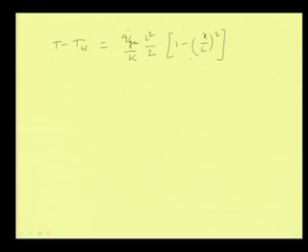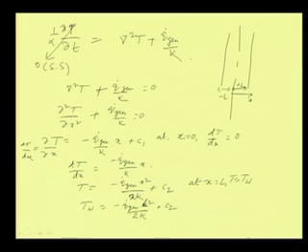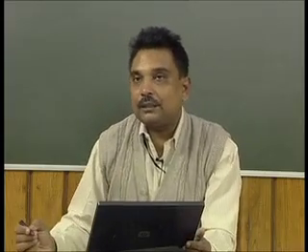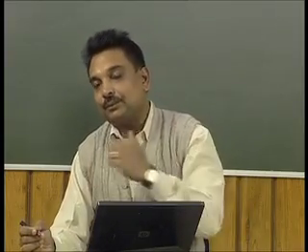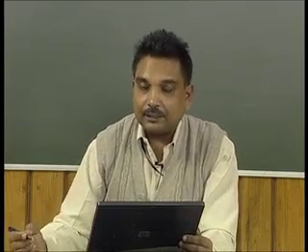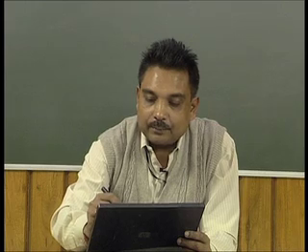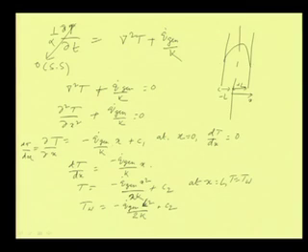This becomes the temperature profile in that plane wall. So, if there is heat generation q dot gen involved, it does not remain a linear profile as we have shown previously. It is going to be a non-linear profile with a maximum at the center point. This is Tw, this is again Tw, and there is a maximum, which is T max.